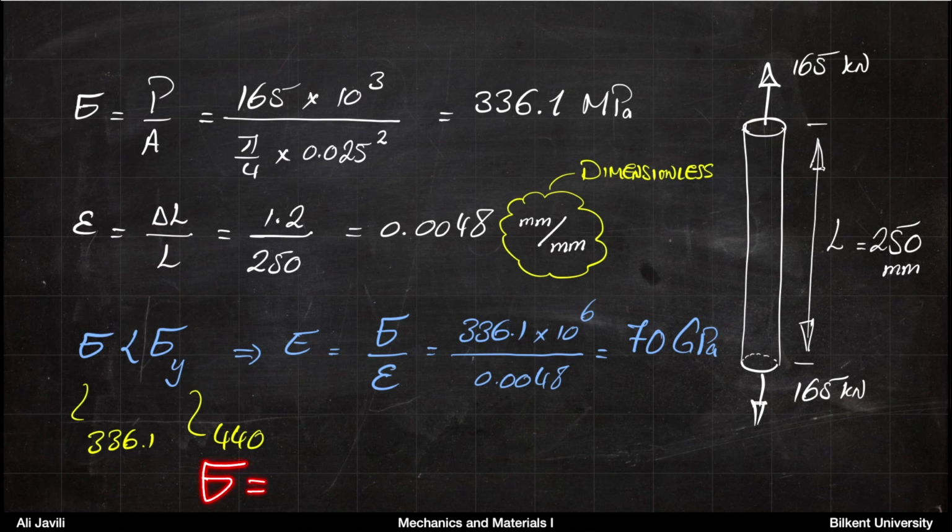That means stress is related to strain via the so-called Hooke's law. And from that, you can calculate the modulus of elasticity, or the Young's modulus, by dividing stress by strain, and that gives you 70 gigapascal. So the modulus of elasticity for aluminum is 70 gigapascal.